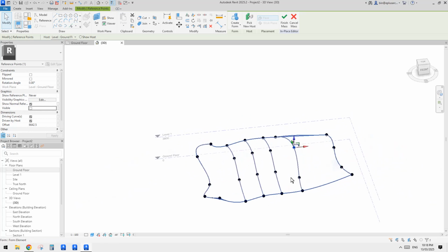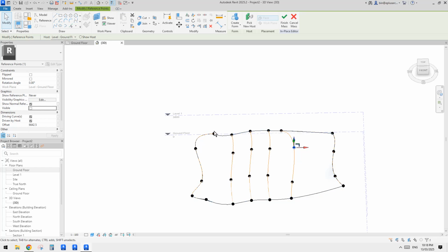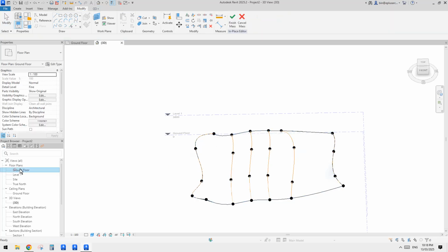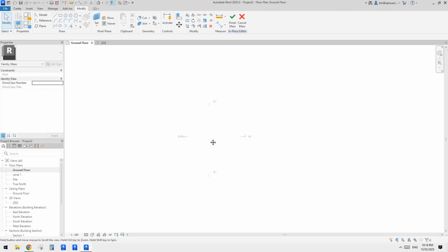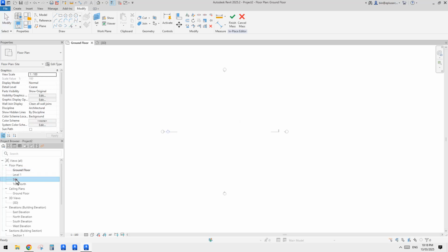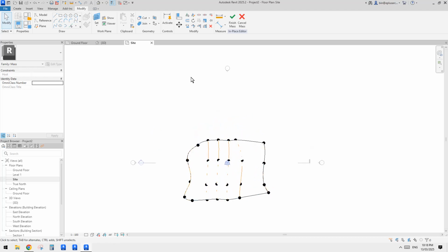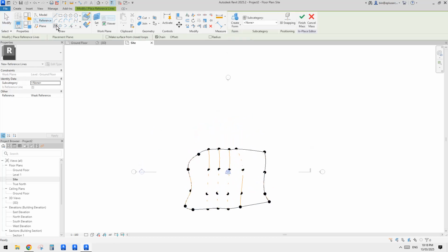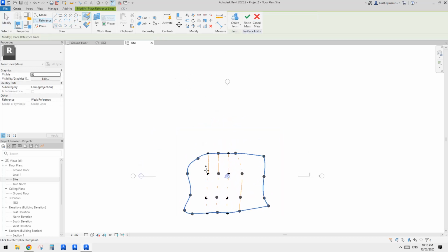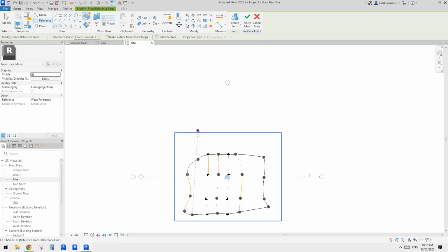So it's better to do it when we only have a flat plan very early on. Where's my point? Oh, it's above the cut plane, so it's not visible in floor plan anymore, but it should be visible in side plan. So early on, try to decide how many profiles, these spline through points, you need.